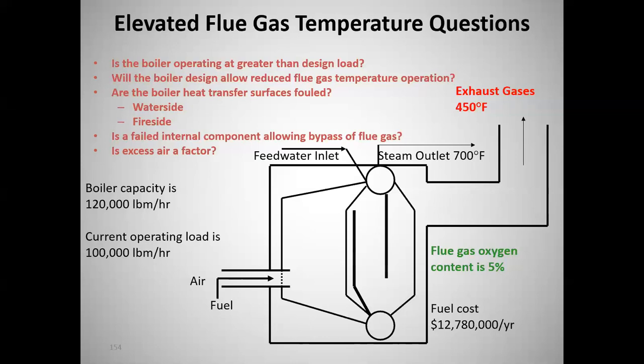It's not necessarily the end of the story, but you just didn't buy a lot of heat recovery equipment and tube surface for your boiler. How are your heat transfer surfaces? When you go down for maintenance and open that thing up, get your little borescope and run it. You can go down to Lowe's and buy one. It won't be as long as that one, but you run it 10 foot down there, you get a pretty good idea what it looks like. Is it fouled? Is it all sooted up on the outside? What's it look like?